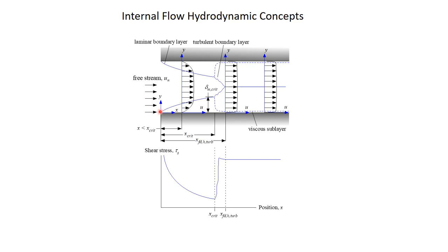So you get this laminar boundary layer. But at some point, before the laminar boundary layers come together, you transition to turbulence, right? You hit that critical position, that critical Reynolds number that causes you to transition to turbulence. And that happens, again, before you would come together as a laminar flow. Once that happens, I would expect a few things to happen, right? The first thing is that the turbulent boundary layer grows very, very quickly, and the reason is because the turbulent viscosity, as we talked about, is so much higher than the molecular viscosity. So that turbulent boundary layer is going to grow very quickly.